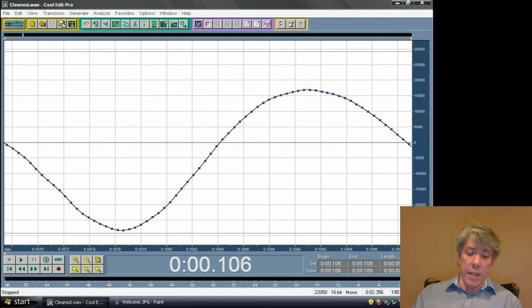But in reality, most analog inputs have 12-bit resolution. And so if you take 2 to the 12th, that's 4,096 different levels that can be measured, which again for most industrial processes is completely adequate.